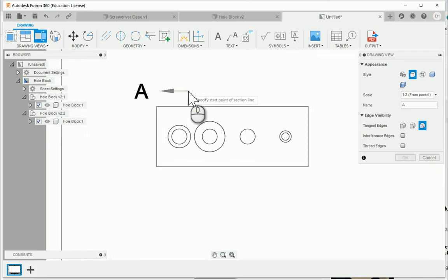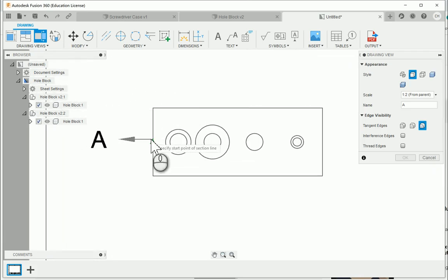I'm going to zoom in here. Now when I go to set this, I do not want to click, I'm just moving my mouse to the center point, which will be noted by a green triangle, the midpoint. And I'm not clicking on the line, I'm going to move out though to the left of it actually, away from that block. And what you're going to see is you get a dashed line that helps you align to that midpoint.